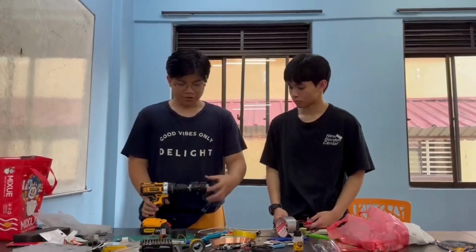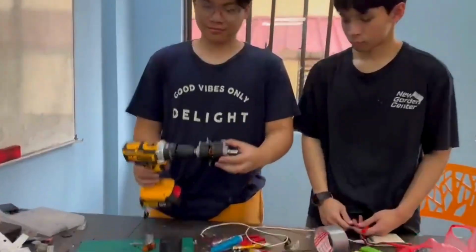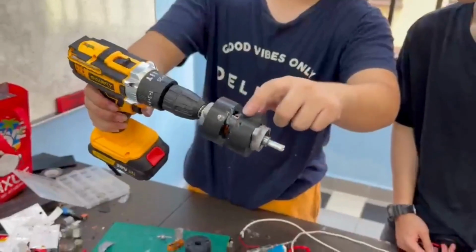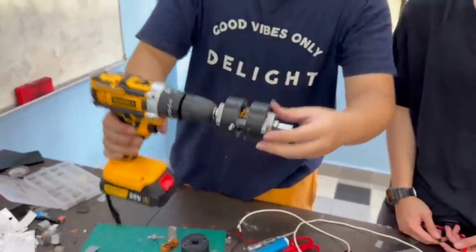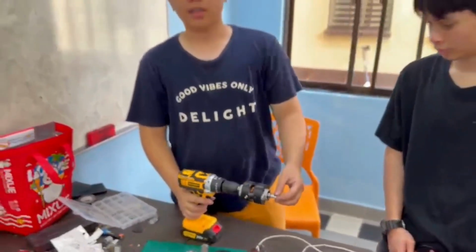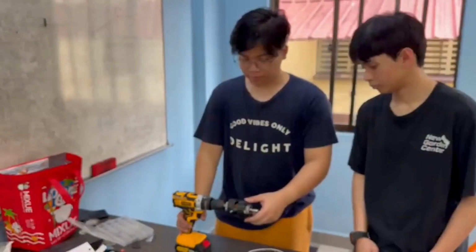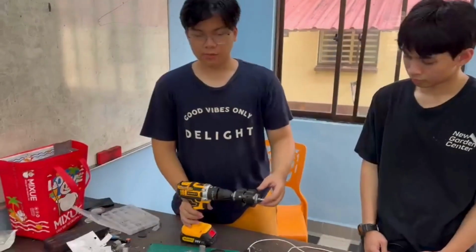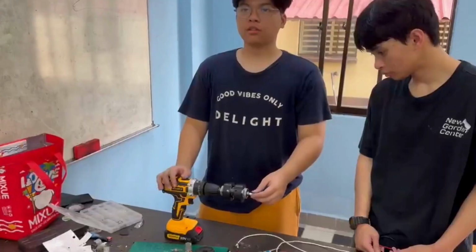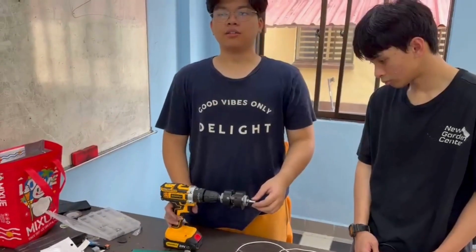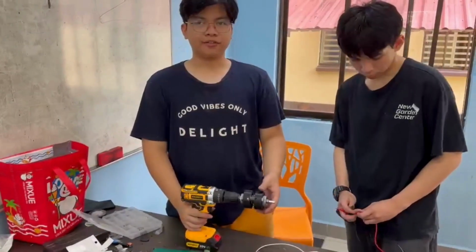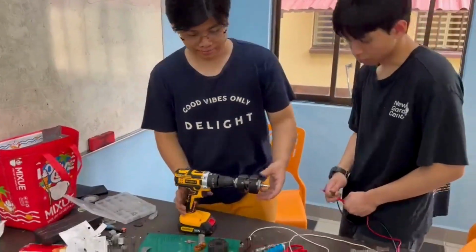So this is our motor. We made it so that you can see the coils and the magnets are also visible. Inside it consists of a spring and carbon brush commutator. It has 10 arms, so 10 commutator connections, and it is also a lap winding, so as to increase the current for this particular generator.